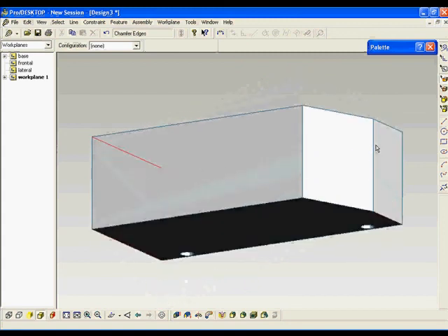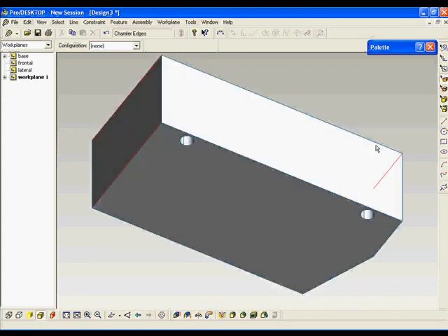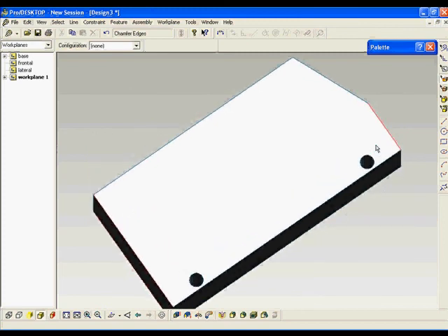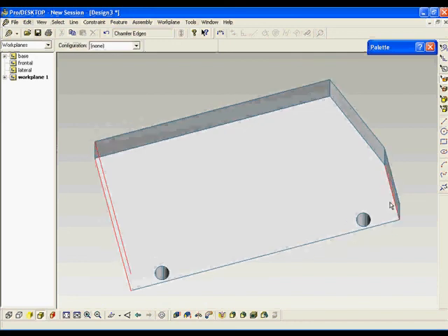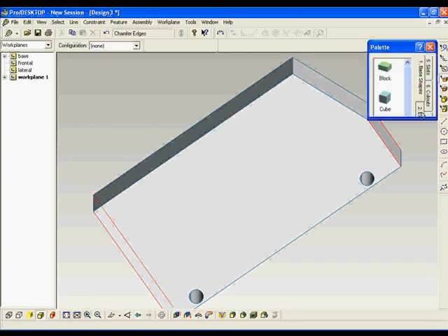You can notice I have 3 of the 4 edges selected in red. I will now select my 4th edge, and then I will issue the round edge command. Selecting that 4th edge now. You'll see edge number 1, hold the shift key down, edge number 2, on the back side edge number 3, and on the back side edge number 4. Move the cursor over, select round edges.